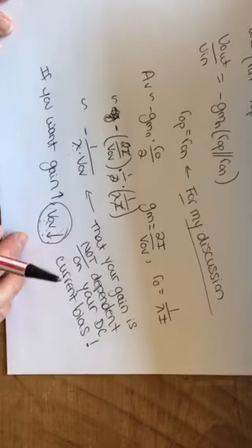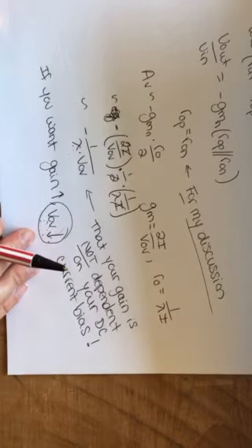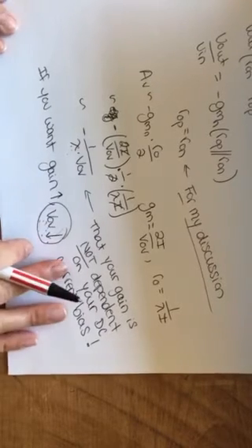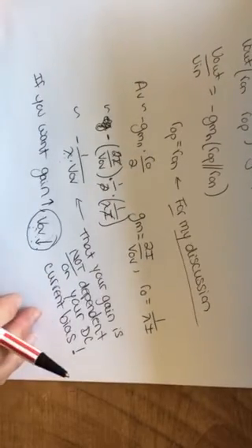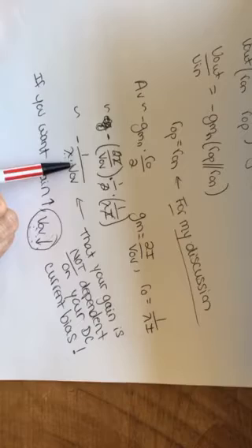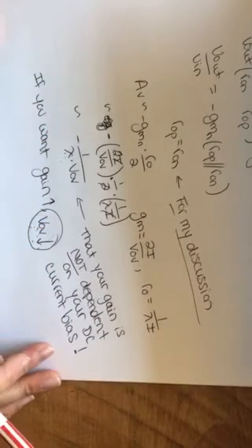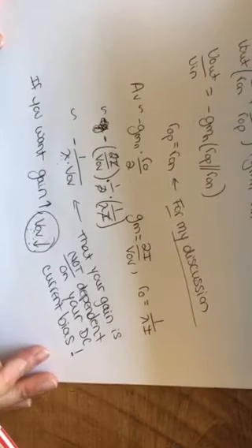So go back and check your DC biases if you end up with a problem with gain. Okay, look at where those devices are actually sitting. Are you actually achieving an overdrive voltage of 0.1 volts? Okay, so in essence, through your DC analysis in this lab, you have set a small signal gain. Okay, so that's how they correlate to each other.